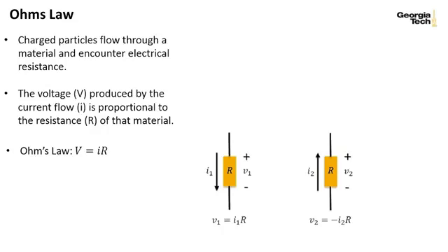So if we have two electrical devices, one with a current I1 flowing from plus to minus V1, then we have V1 equals plus I1R. If you consider the other device, V2, where we have current flowing from minus to plus, V2 equals minus I2R. So the same mnemonic device that we've used all along, whichever sign for the voltage you get to first, you can use that one in your calculation. For V1, the current gets to the plus sign first, so it's a positive current. When calculating V2, the current gets to the minus sign first, so we use a minus current.